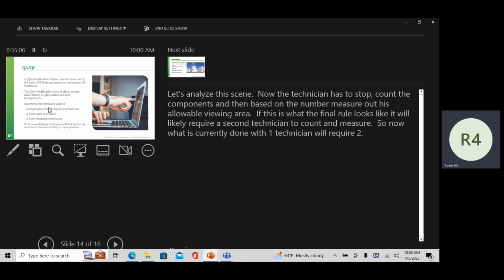LDAR, right? And no disrespect to Method 21 LDAR, it has been and still is a very necessary monitoring and reporting protocol, but this is different. You're dealing with a different breed of cat. But it's good because your weekend warrior's no longer gonna be able to just pick up a camera and go out there and say he scanned your facility. And the regulators are gonna be able to ask them the question, hey, how many hours do you have? Make sure you're tracking it.